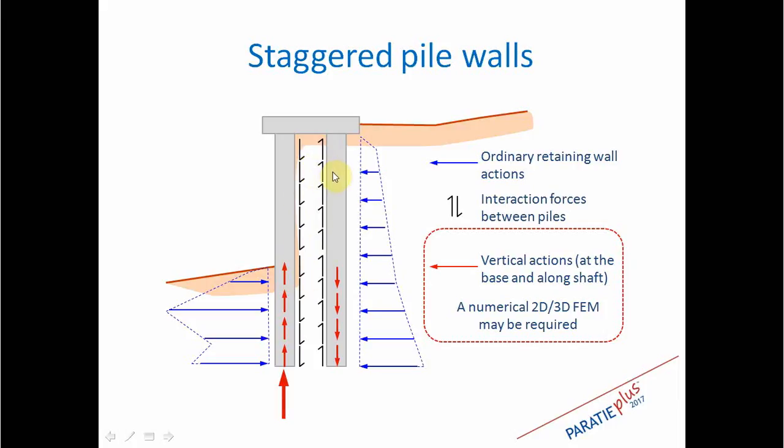that can be provided either by the soil in between piles or by the grouting that interferes from each pile to the other piles. And if the distance between the two rows of piles is big, there is also a resistance due to each pile acting as a vertical loaded pile, and we may have a base resistance if the pile is in compression, and also a shaft resistance.